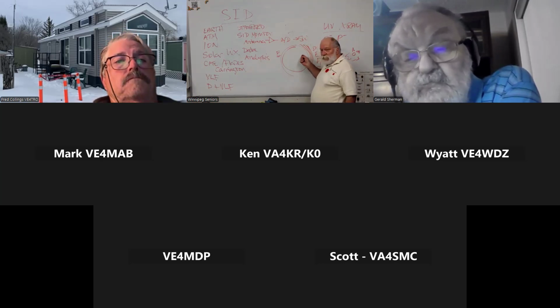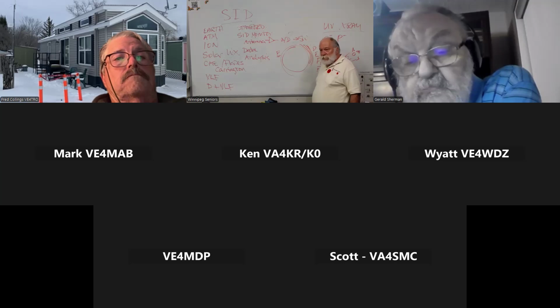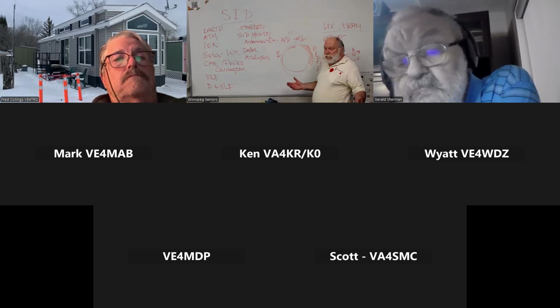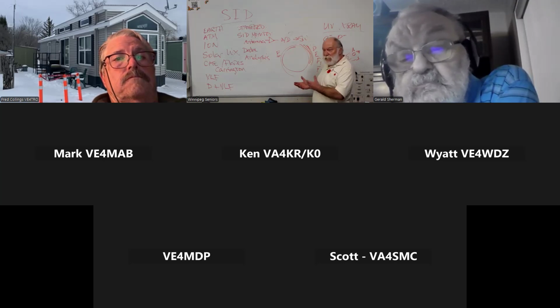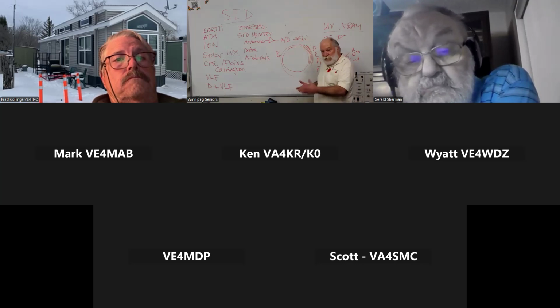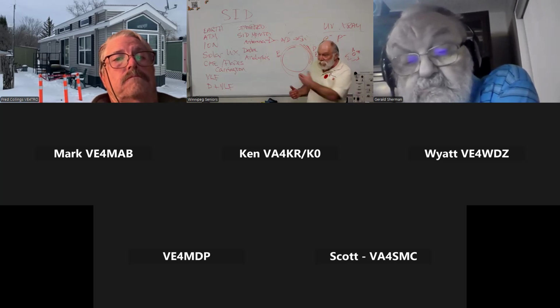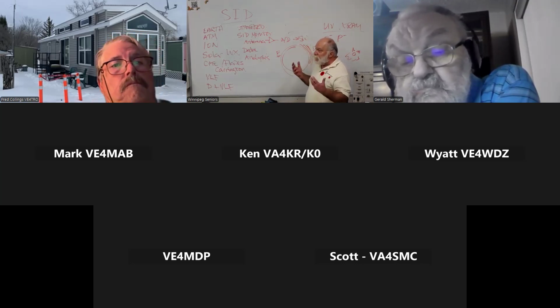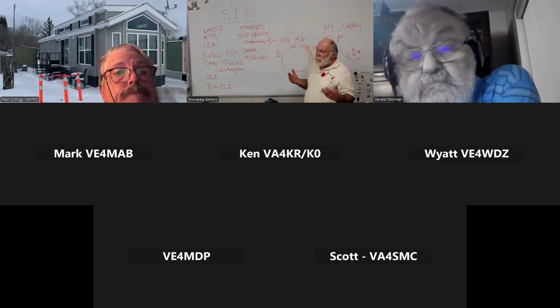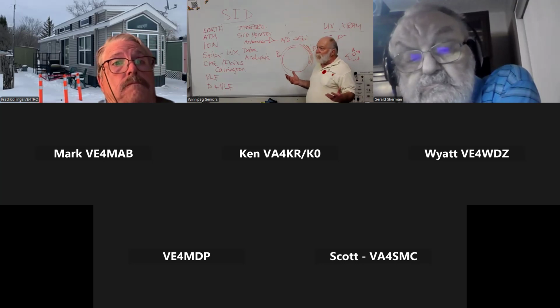It doesn't eat very low frequencies. By very low frequencies, I'm talking about like 22 kilohertz VLF. As a matter of fact, it behaves almost like the F layer does to HF. It bounces off. And all of a sudden, I'm thinking, oh, okay, I sort of get this now. The D is not eating VLF signals.